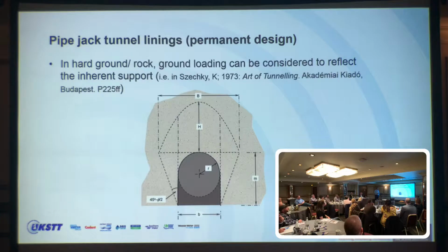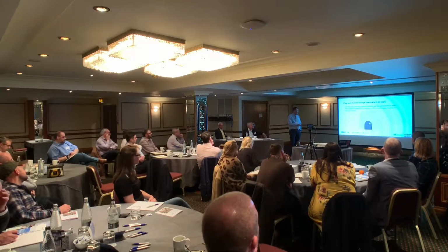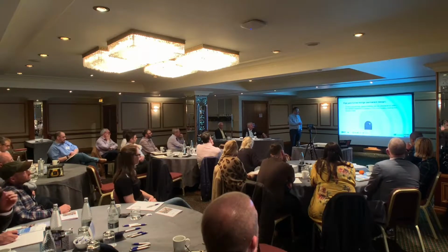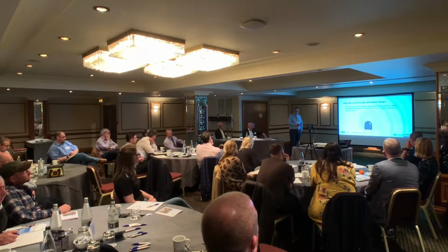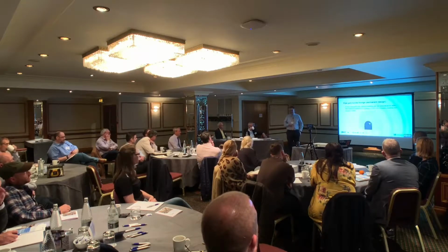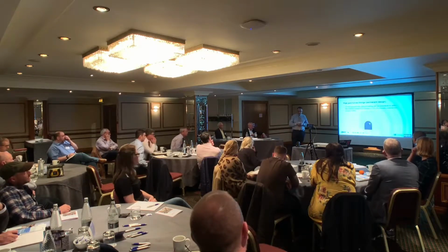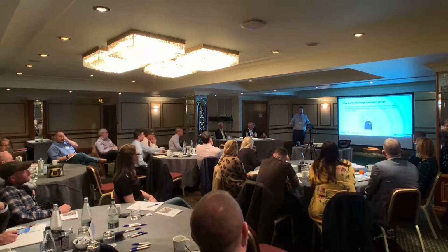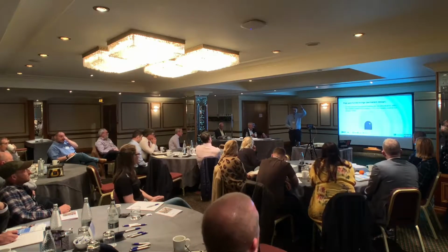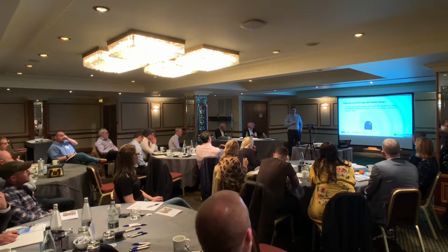If you're into rock and things like that, again, I've included a reference there for anyone that wants to go into it. But you can look at more complex loading. So again, it's a bit of a variation where you're looking at the tunnel itself, and then you're taking load off the side, and you've got the arching effects. In terms of loading, it's very important to understand the conditions that you've got, because as I'm sure you can appreciate, if all you were ever doing was considering a full overburden depth, then you'd be shattering pipes all the way through the country. And in practice, that's not what happens.